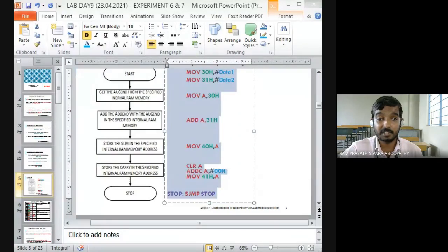So here also I am doing the clear operation. The accumulator is cleared, correct? Yes. Here also we are clearing the accumulator. So after that, what I am doing? After the clear accumulator operation, what instruction have I used? On seeing that program, yes. After CLR A, JNC skip. Thank you. What does it mean? JNC means what? Yes, very good. Jump if no carry.